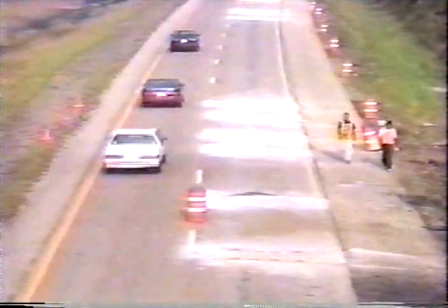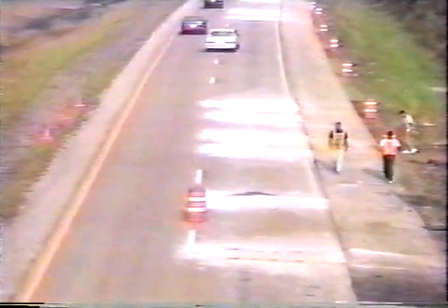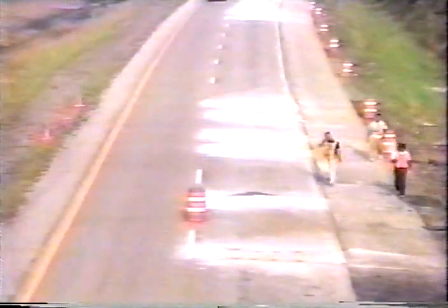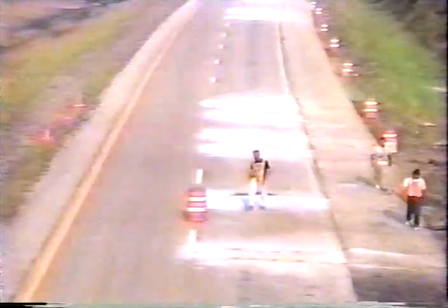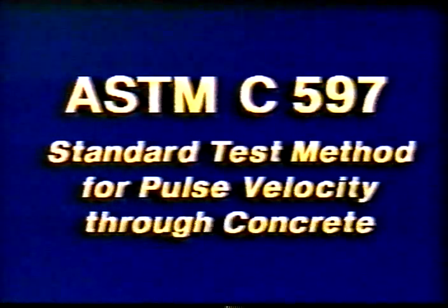As stated earlier, in-place strength can be used as a criterion to open bridge deck overlays, pavements, or full-depth patches to traffic. Again, however, strength development with time is typically different under laboratory isothermal and moist curing conditions than it is in the field while subjected to a range of air temperatures. Pulse velocity testing according to ASTM designation C597 can be used to monitor in-place concrete strength development.